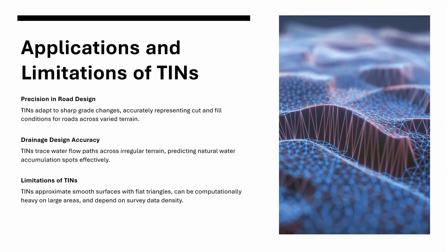So, where do TINs excel? TINs shine in scenarios where precision and local accuracy are essential. In things like road design, roads can cut across hills, valleys, and ditches. A TIN can adapt to sharp grade changes and accurately represent the cut-fill conditions along an alignment.